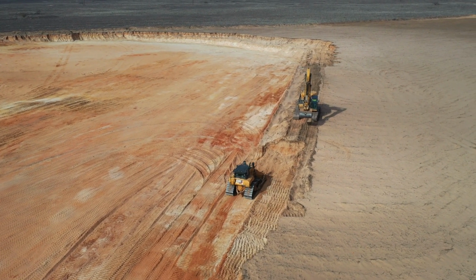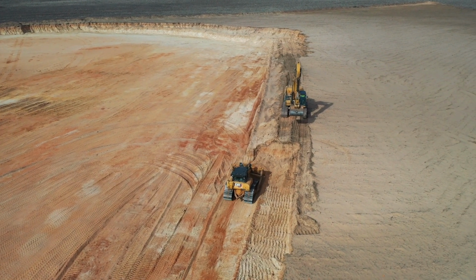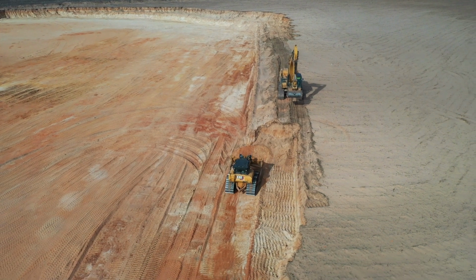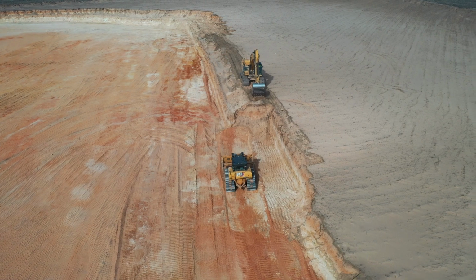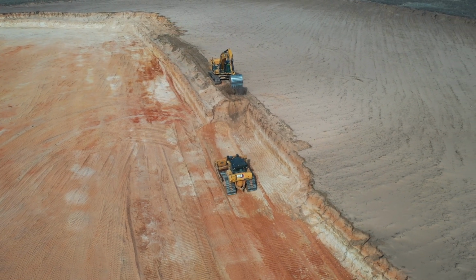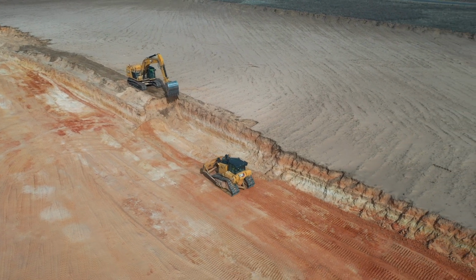Use technology equipment or a spotter to assist equipment operators when working near high walls. Be attentive to changes in ground conditions and visibility. Watch for surface cracks and loose material near high walls. Keep the dozer blade between you and the edge when operating close to drop-offs.